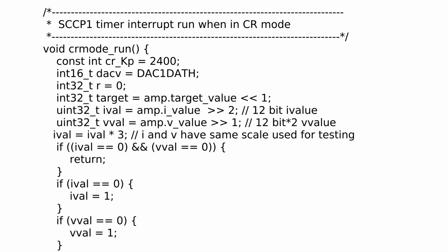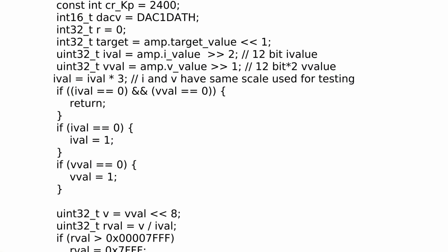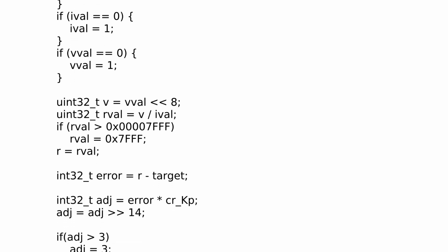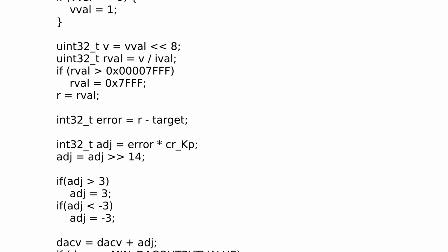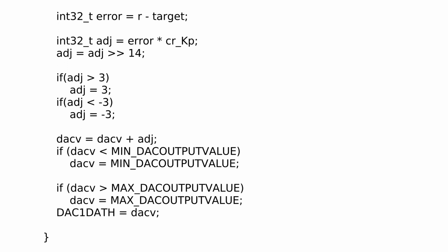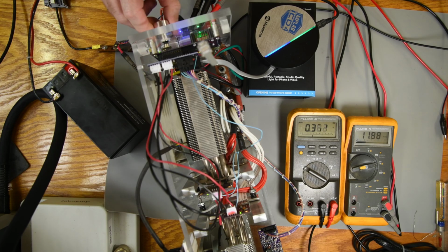The constant resistance mode is still giving me some trouble. It wants to have a bit of ripple at a higher resistance setting. I think that may be just the coarse current stepping of the output. If so, it may only be usable at very low resistance settings. It has worked fine on the DC power supply, but that can only supply 5 amps, so I want to test it at a higher current and see. So I've got a small lead-acid battery to put on the load. Should have no problem supplying 10 amps.